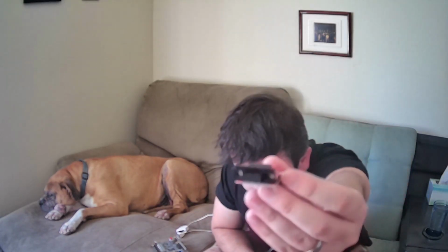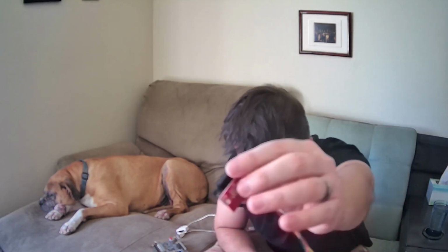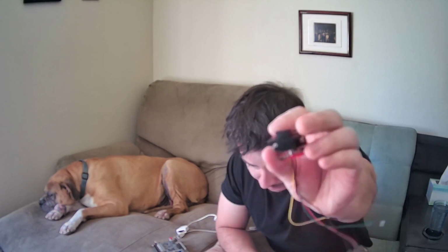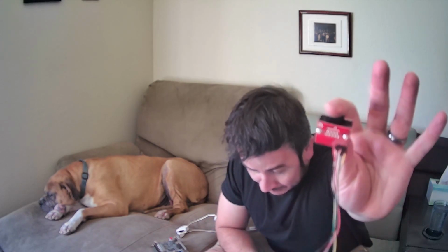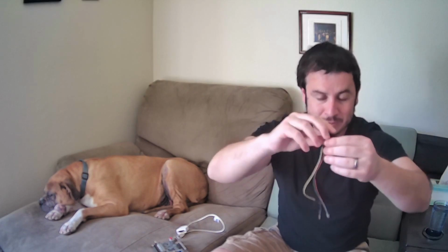This guy is a level shifter. It has the same 9-pin connector that's on that adapter, and it breaks out 4 pins. These 4 here, and I soldered on these wires extra. I got these little hookup cables off of Amazon because they're pretty cheap. It was like $3 for like 40 of them or something. This is a really convenient little thing to both make sure that I'm not going to burn up my FPGA by connecting external hardware to it, and also it's a convenient breakout for the wires I actually care about.